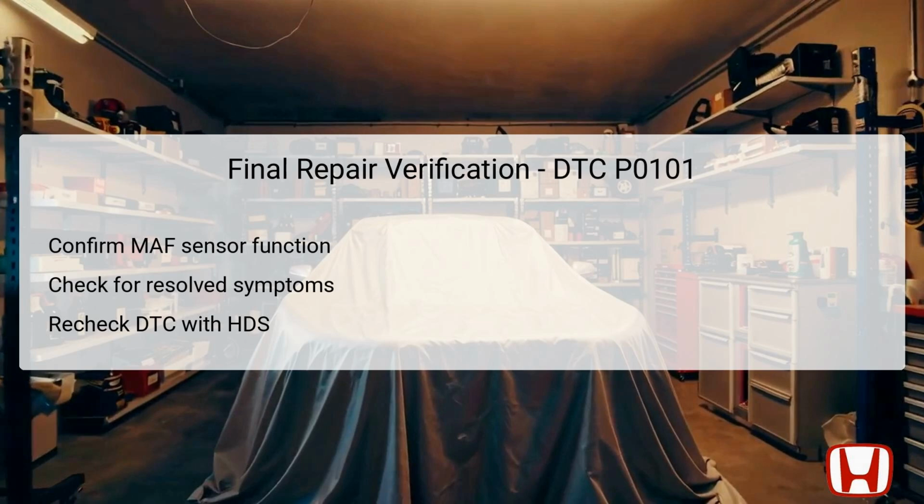It's also crucial to assess whether any symptoms that arose before repairs, such as increased fuel consumption or poor engine performance, have been resolved. Finally, clear all DTCs from the system and perform a follow-up test drive, rechecking for any new occurrences of DTC P0101 or related codes through the HDS. This step ensures that the problem has been fully resolved before concluding the repair process.